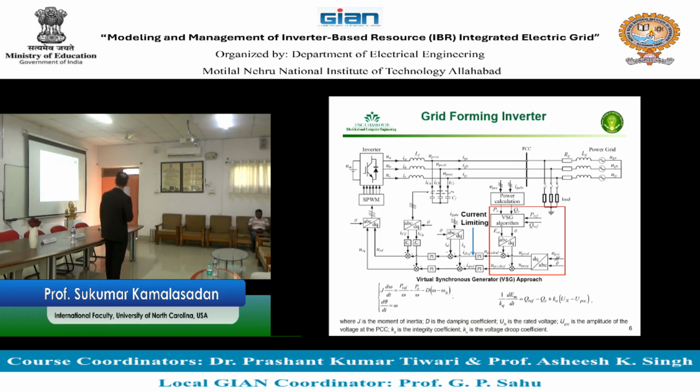If you take an inverter like that, the output of the inverter will be 3 voltages and currents. On the DC side of the inverter, we assume there is a DC source connected, which could be a battery, photovoltaic and so on. Modeling of the DC source, we conveniently ignore, and we say that the DC source will be there and it will provide the voltage.